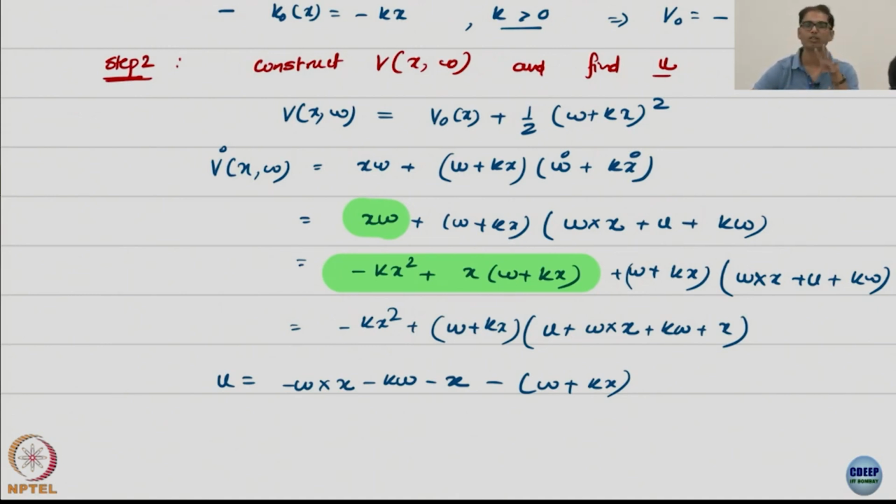But anywhere where you use CLF based design, which is whatever we are doing, will always give you robustness for free. Even if you add disturbance to your simulation, and we will give you assignments in this direction, where you will add noise, you will add disturbance and so on, and you will see that your performance remains close to ideal. You are not going to deviate, it is not going to destabilize your system. Okay, so that is of course one of the features.